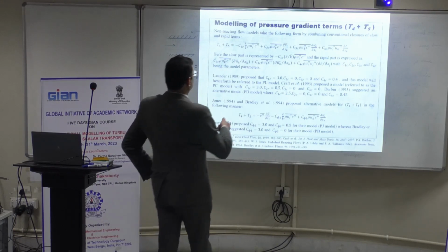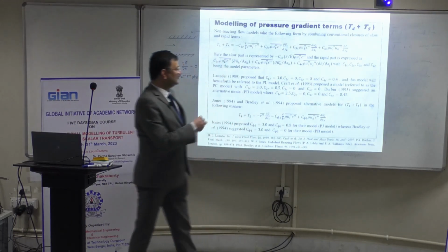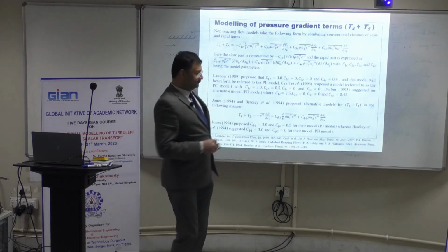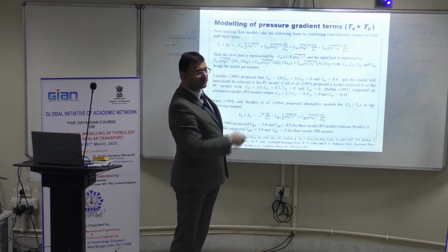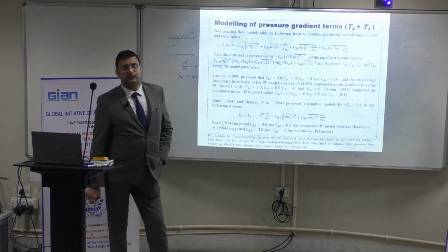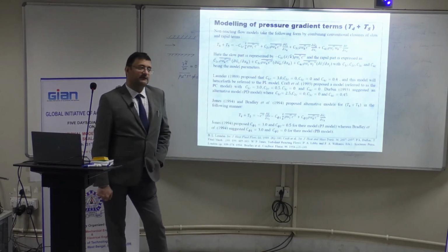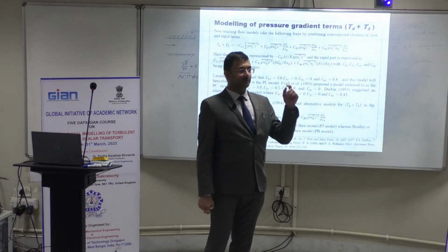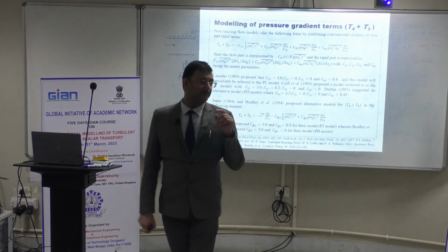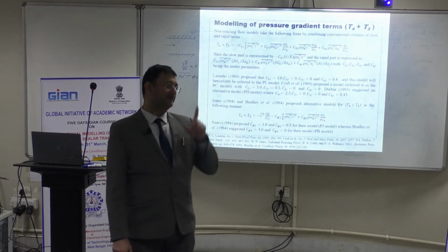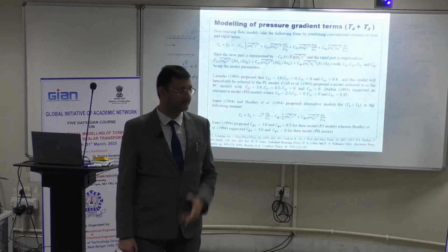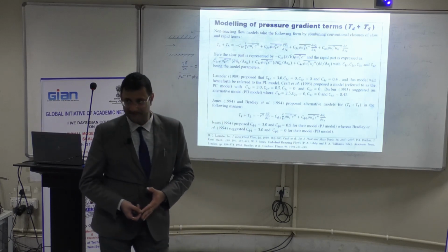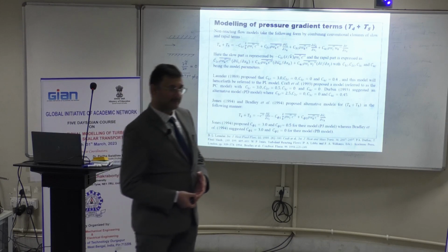Okay. For T4 and T5, a variety of models have been proposed. There are a huge number of models, which I have indicated here. Some of these models, for example this class, were proposed for RANS simulation of non-reacting fluid. As a result, the T4 term, which had c double prime bar and the mean pressure gradient, never appeared, because that term goes to 0 in the case of incompressible fluid.